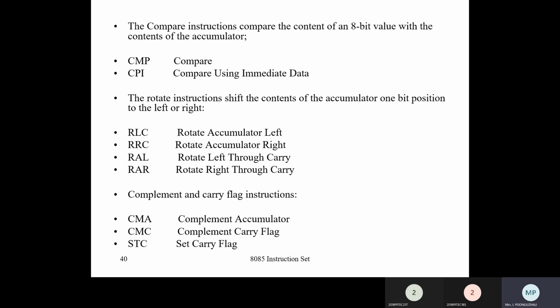If no flag is set, A is greater. If the sign flag and carry flag are set, A is lesser. We have to check the flag registers to finalize which number is greater or lesser.